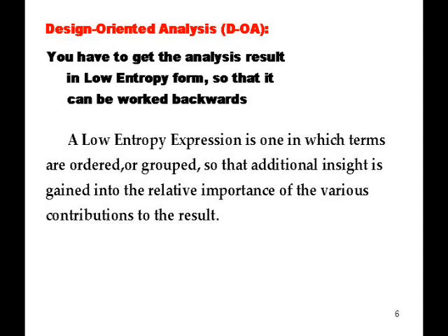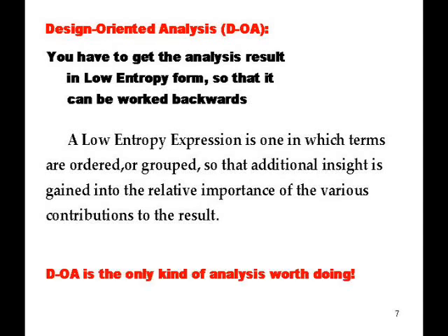And so the next question is, what are you going to do with all of that? And the answer is nothing, because you can do an eyeball kind of analysis to try to work back to see where those components came from in the circuit, but that's a losing game in anything that's at all complicated. So that's the main point about design-oriented analysis. You have to keep control over the algebra and get a result that you can use backwards.